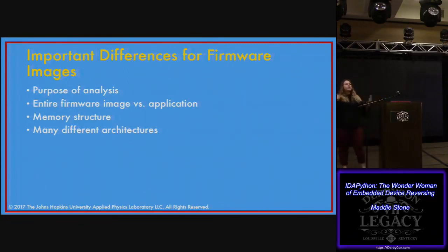Are they creating new connections? Are they grabbing new data? When we're looking at a firmware image, though, we care about how this firmware is controlling GPIOs, because the only reason this processor exists and this code exists is because it's controlling some physical functions outside of that chip.